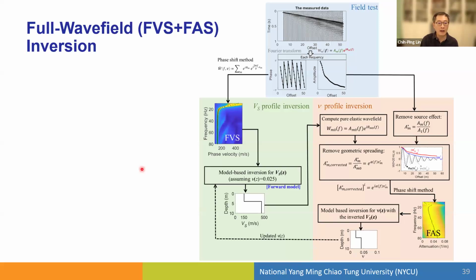We have also worked on field data. We collaborated with a French company to get offshore data, and we did offshore inversion to get the shear wave velocity profile. We also compared with what they are using, fundamental mode inversion. It works very well synthetically, and also quite well on real-world data.